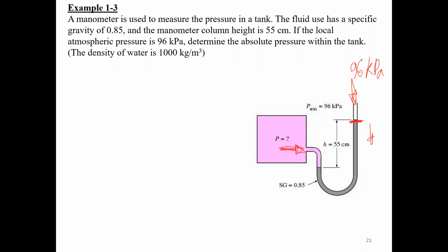When we reach this state, we know that, from one side, the pressure of the system is trying to stop the pressure of the atmosphere. So to find out the absolute pressure, we should add this P, which is P gauge, to the P atmosphere here. So we add this to this one to find the absolute.